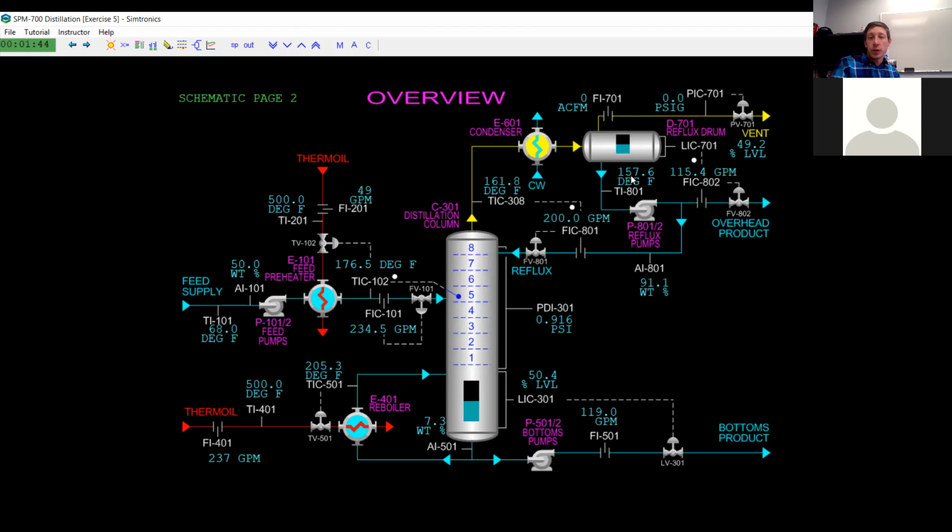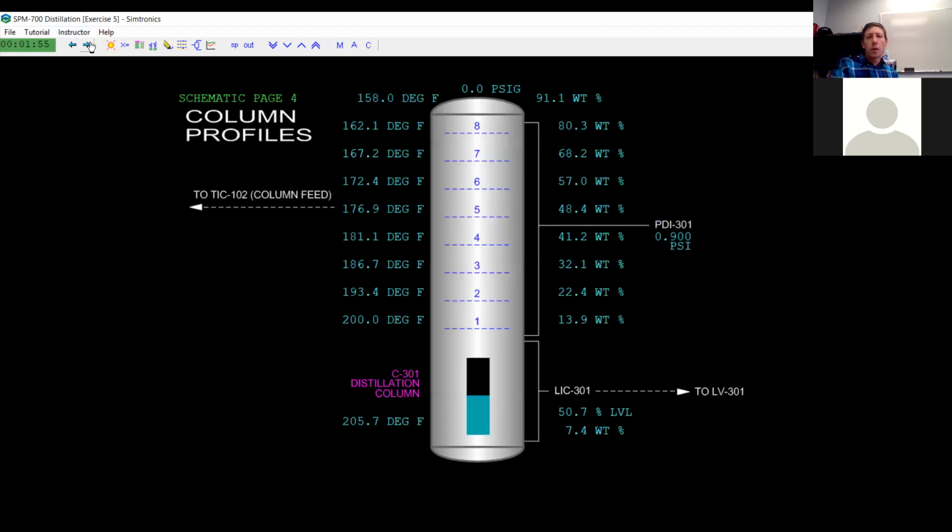First, we think, oh, that's no big deal, just a little bit hotter. But watch what that does to the rest of the column over just a few minutes. Watch what happens to these temperatures. All of them are going to start going up, because we're not cooling the material at the top of the column enough, which means we'll have higher and higher temperatures throughout the column.